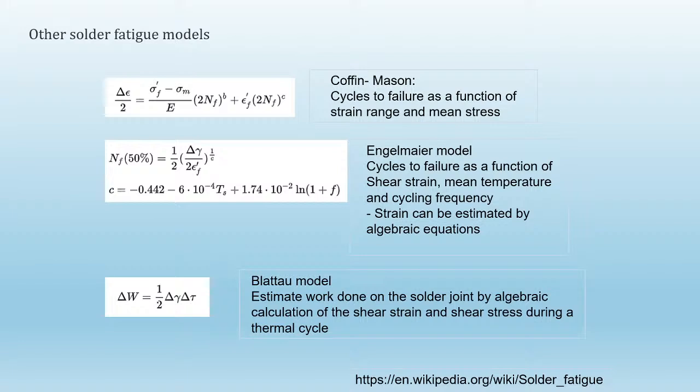It's pretty straightforward, but I think the main thing out of that is that you want to mesh things carefully and don't use any contact elements. Make sure you have all of your mesh near the solder node to node matched, and then the results come out very accurately. I've verified all of Dr. Darveaux's models that he published, and as it was accurate then, it's still accurate now. So we're pretty confident in getting these right results.